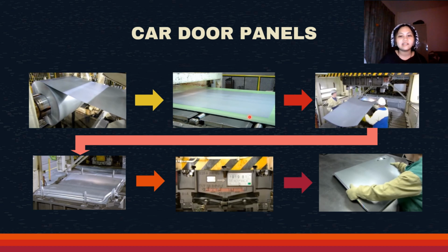Large blades are used to slice the carbon steel roll into desired lengths, producing sheets called blanks. The blanks are then brought over to a powerful press, which offers a better view of the stamping process. The press forces the blank into a die, giving it a basic shape of two car door panels. The design of the car door has been engineered for better aerodynamics and strength.